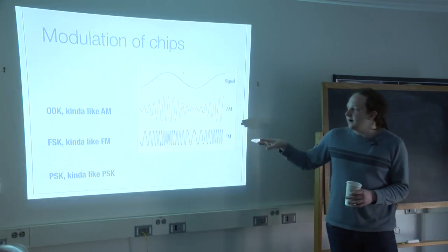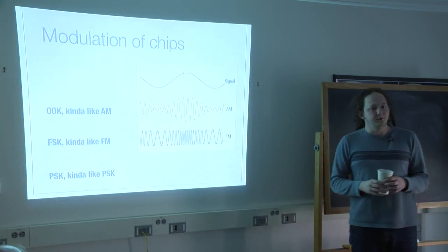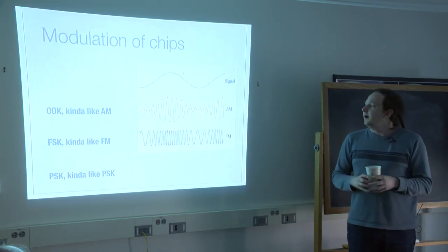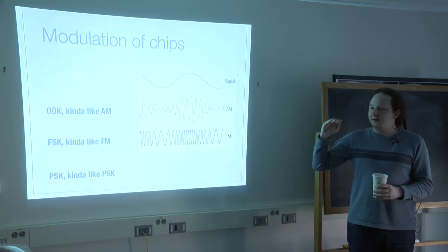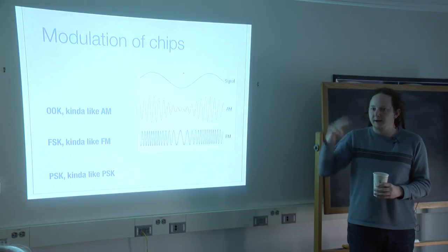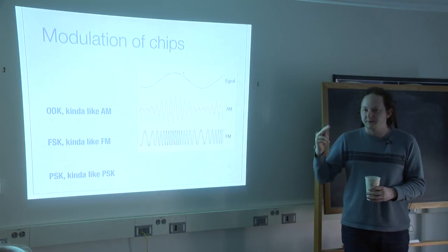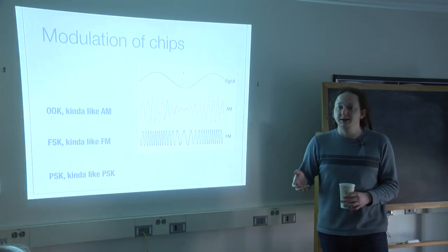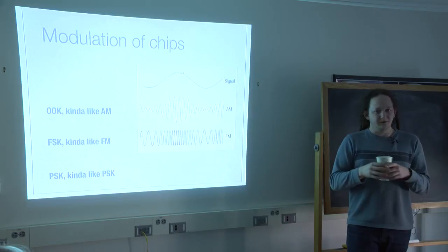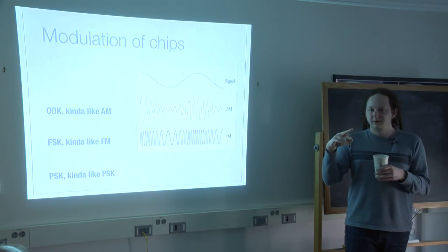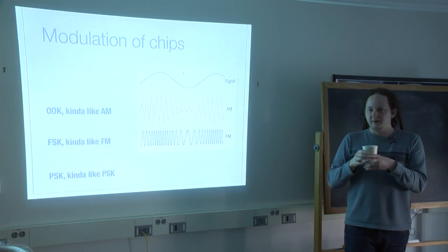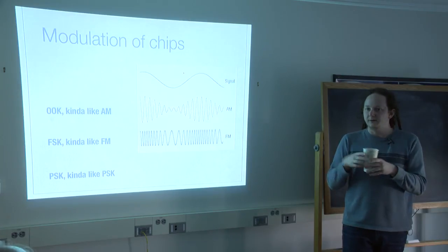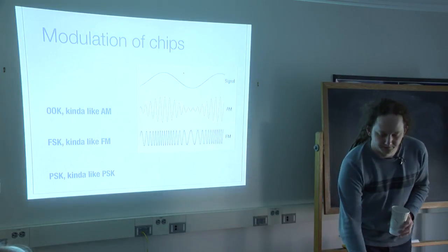Frequency shift keying is kind of like FM, in that you transmit one of 2 frequencies, or sometimes 4 frequencies, and the bit is indicated by whether you're a little bit beneath or a little bit above the center frequency. And then you have phase shift keying. The idea is that you invert the carrier wave in order to mark the bit, and then the receiver compares that to a reference that's been trained on your carrier wave to see where the flips are.